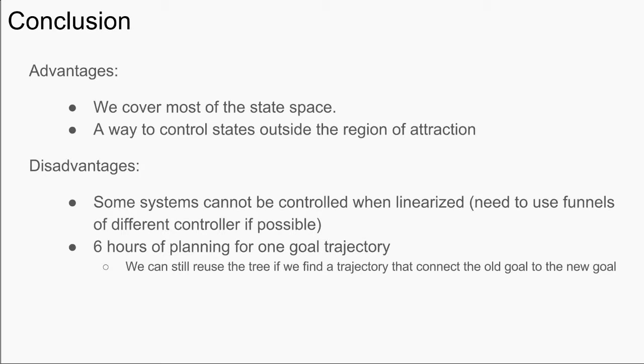Another disadvantage is that since LQR is linear, it's based on a linearization. There are some systems which cannot be controlled when they are linearized. For such systems, this method cannot be applied.